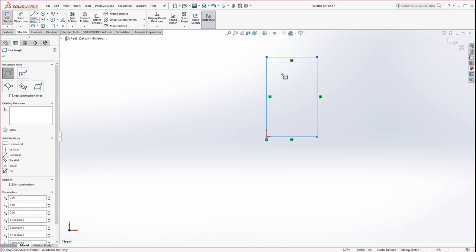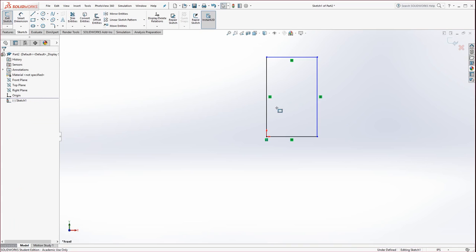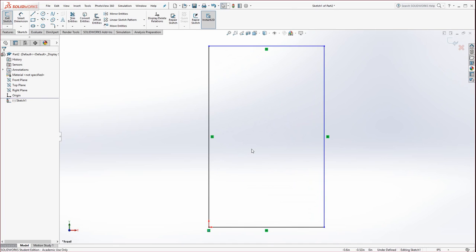But needless to say, these are very useful if you want to see them. If you hit the escape key on your keyboard, it will disable the line tool, or the rectangle tool. So I just hit escape in the upper left corner of the keyboard to do that. Now to fit this to the screen, a fast key for that is just the F key, wedged between the D and the G keys. That's zoom to fit, and that will zoom it up on your screen.